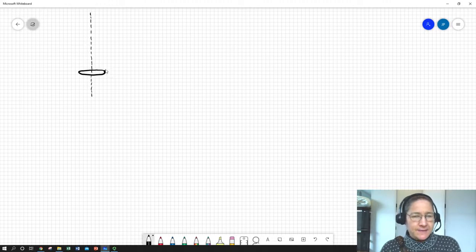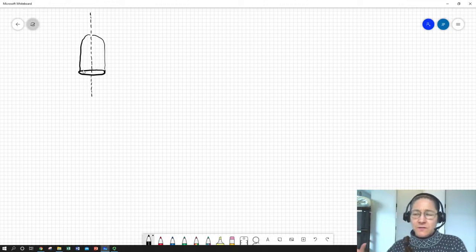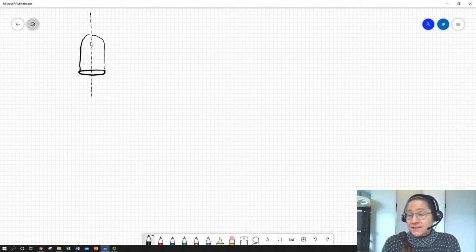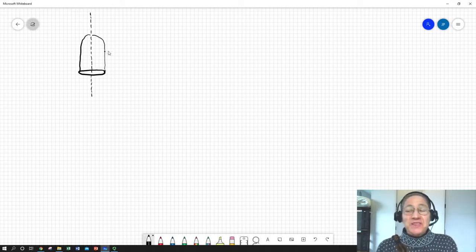where we use these principles to look at a spout or a pipe or something like that, where we could take a little section of the moving fluid, look at it as our reference volume, and then treat it in a way as a statics problem, where we looked at the forces that would be generating the impulse necessary to change the momentum of the fluid moving through it.